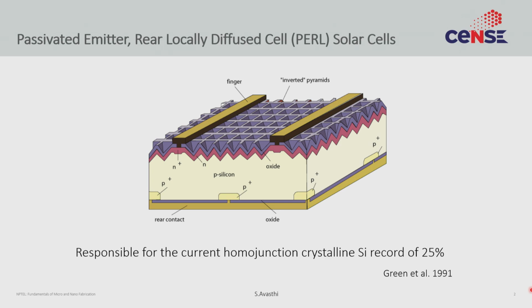So silicon solar cells are also PN junctions. The only difference is that they are PN junctions optimized for light absorption. So typically one of the contacts is either semi-transparent, or completely transparent, or has a metal grid, something that allows light to enter the cell and be absorbed in silicon. So that's point number one.